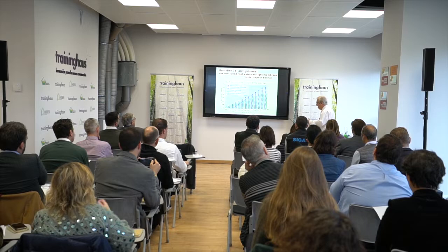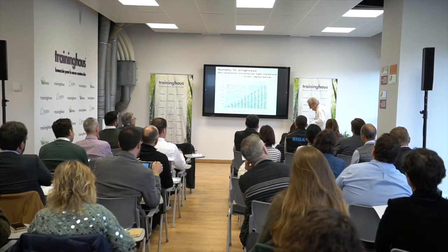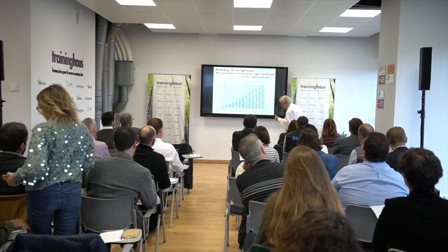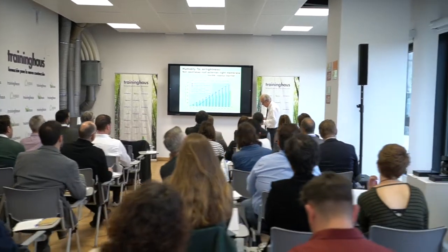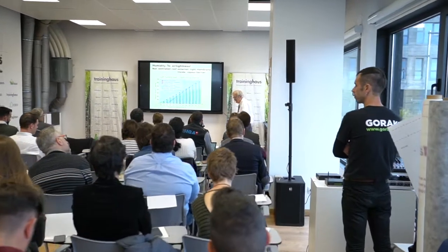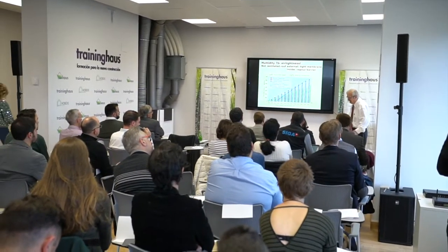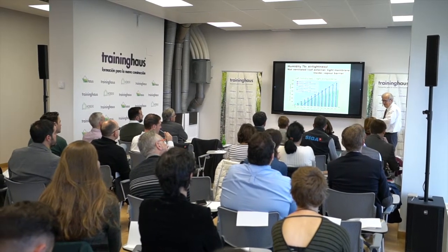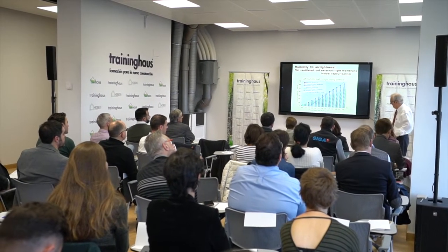So what is driving the higher humidity into the construction by convective vapor flow is doing that during the winter when you don't like it to happen, and it's not working during the summer where you would need it for the extra drying.